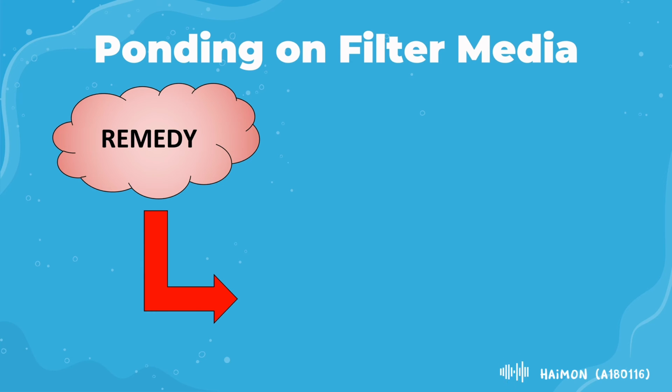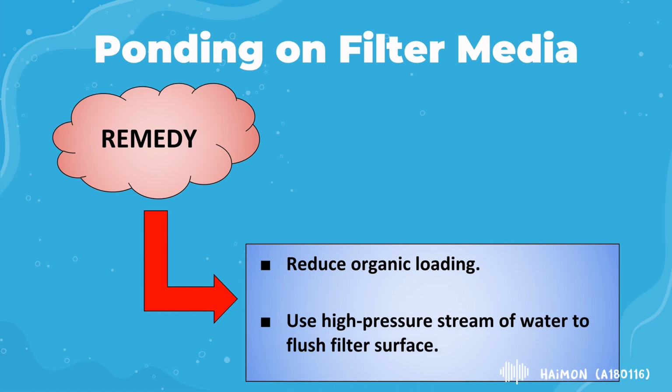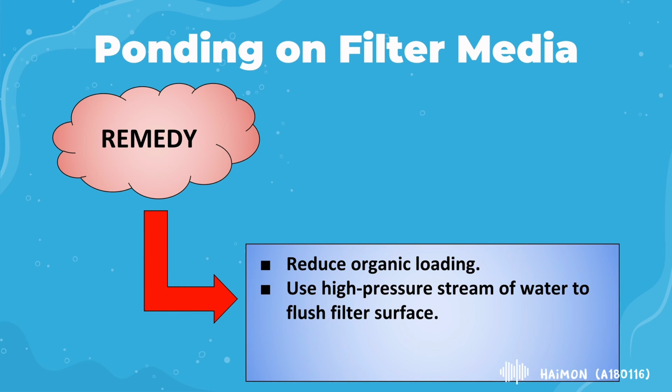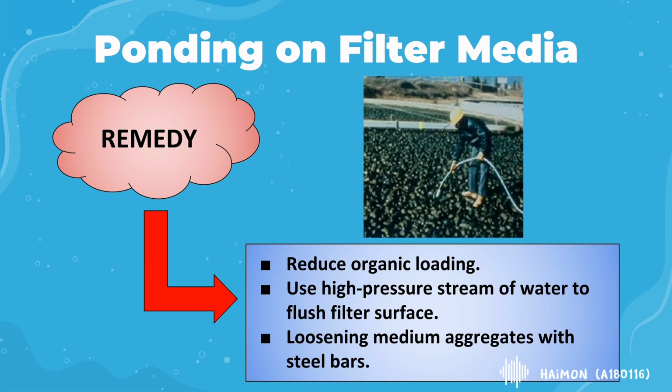Some of the remedies for this problem include reducing organic loading into the filter media at designated times and using a high pressure stream of water to flush the filter surface, simultaneously loosening medium aggregates with steel bars.